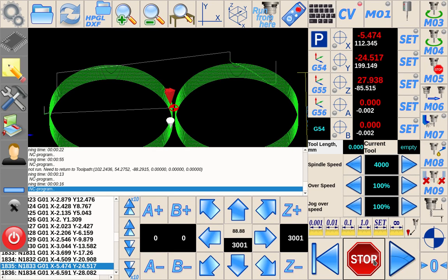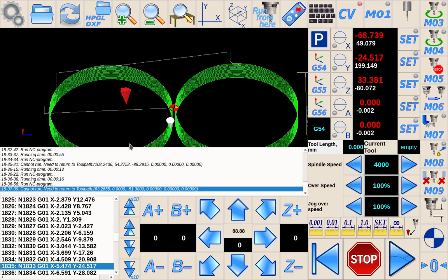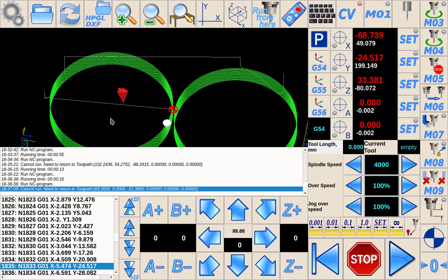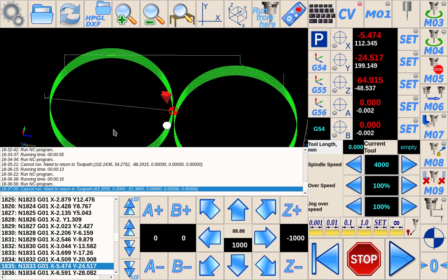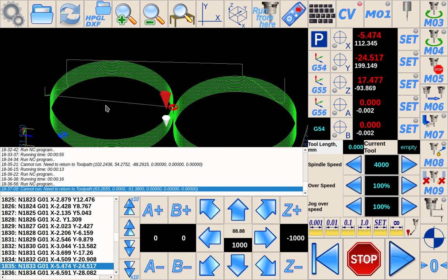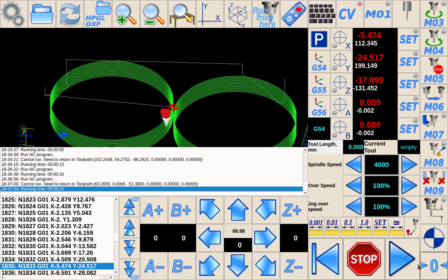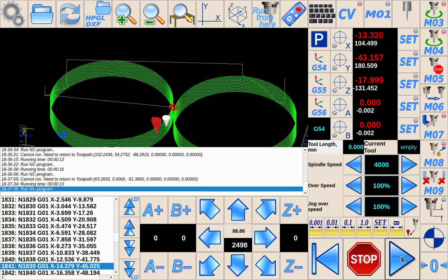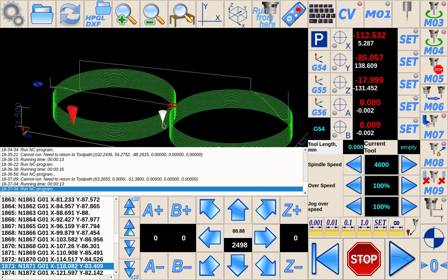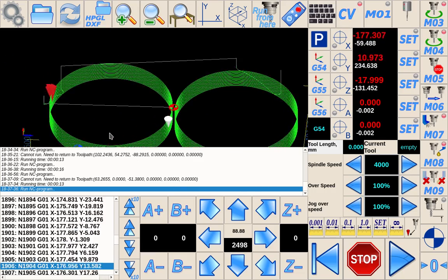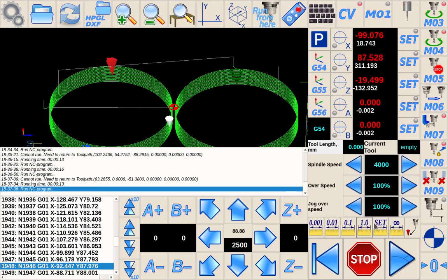If I move up and, for example, the X axis and try to play, it blocks starting, and the system asks to return to toolpath position, and I can press the R button, it moves up, moves XY, moves Z, and then I can press play, and it resumes cutting.